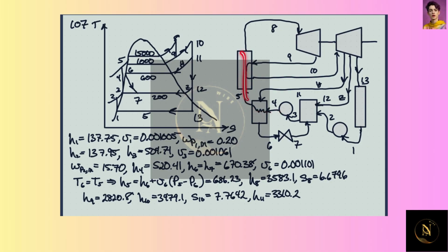The boiler pressure is 15 megapascals. Coming out of the high pressure turbine is 1 megapascal, which is what's going into the low pressure turbine. The first bleed is at 600 kilopascals, the second is at 200 kilopascals, and the condenser operates at 5 kilopascals. We have a fraction Y coming off at the first bleed and a fraction Z coming off at the second.